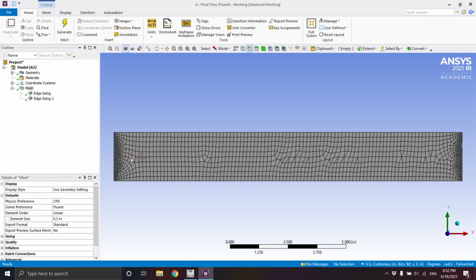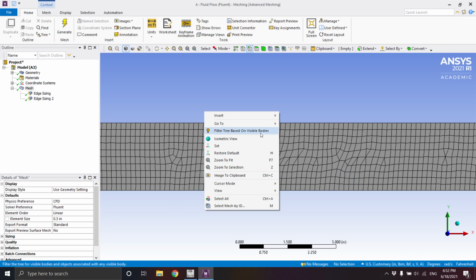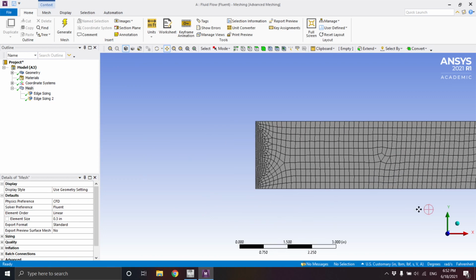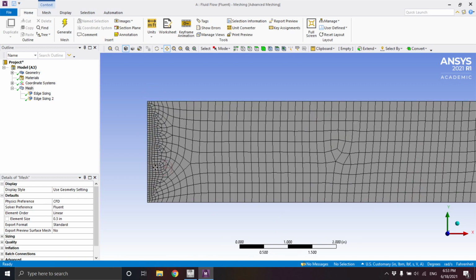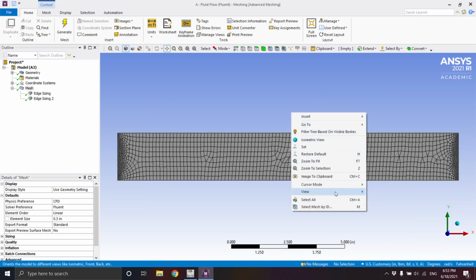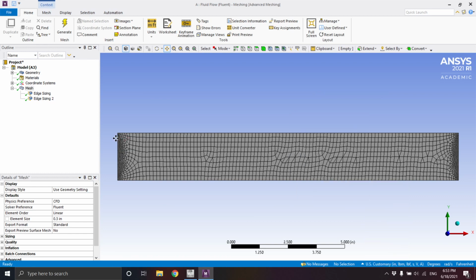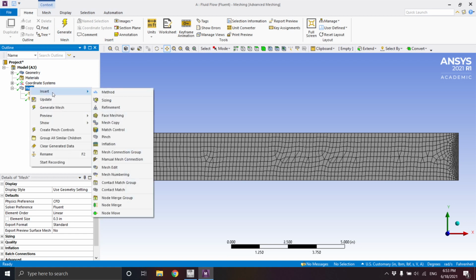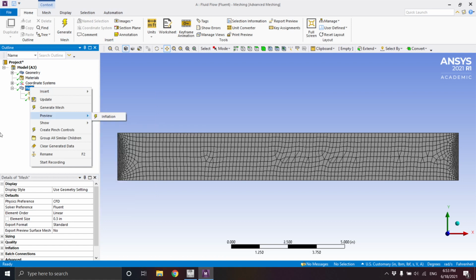And we can see that it's gonna give us somewhat of a very similar to a hybrid meshing, because we have here on the edges on the right side and the left side some unstructured mesh, and we have a structured mesh in the middle. We can always fix this, and we can redefine our mesh with another important tool called mapping.